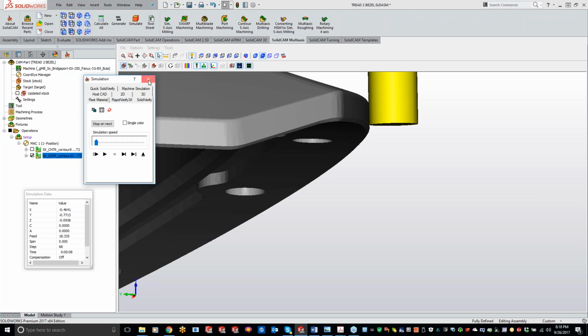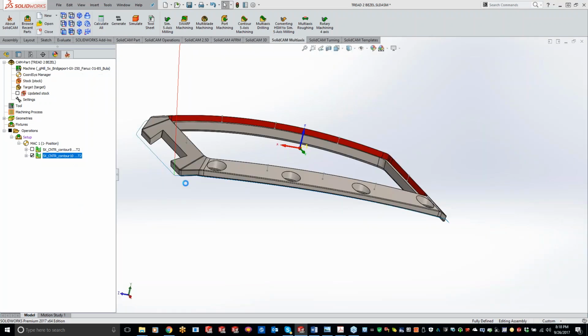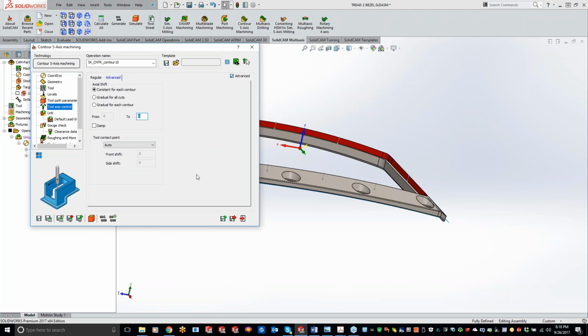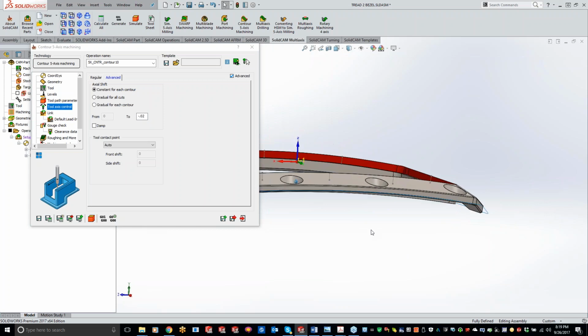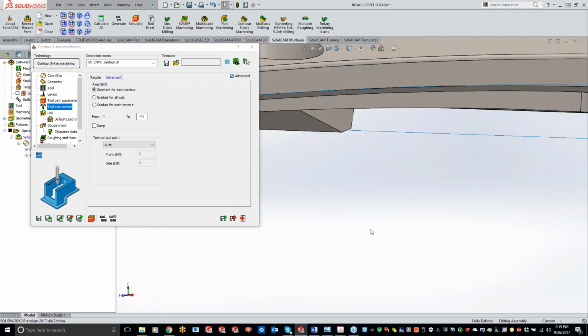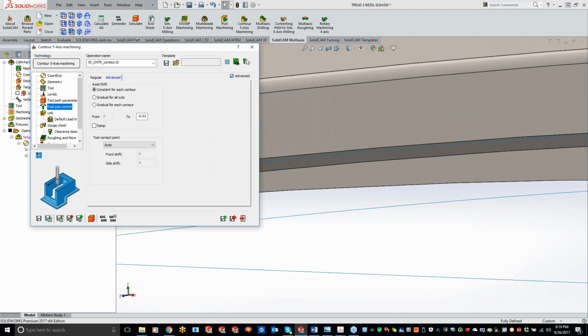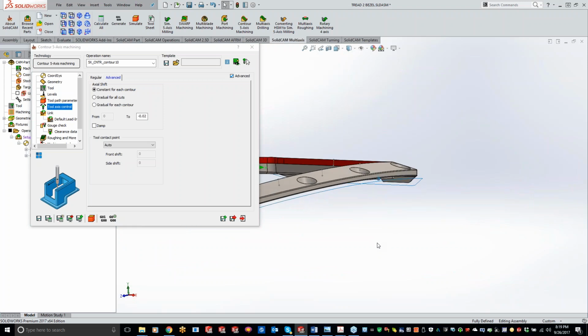So let's hop out of here for a second. If we go to the tool axis control under advanced, I can put a minus 20 thou in there. Let me zoom in on this toolpath, and we should be able to see it jump down. Now if I do a save and calculate, you'll see that my toolpath definitely jumped down for us, so going a lot deeper.